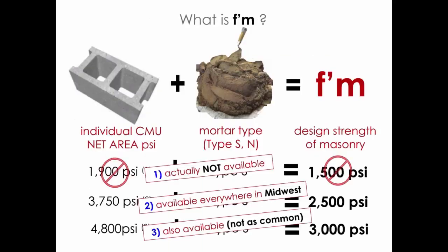All right. So last little bits here, and then just a little update, because maybe the last time I talked about this, maybe I was talking about the 2011. Within the 2013 MSJC or 2016 TMS codes, the new masonry codes, you can actually see these design strengths, block strengths that you need to get the higher F'm, relaxing a little bit. The one in the middle, the one that I'm saying is kind of a standard, things that we can use across the country, 3250, right?